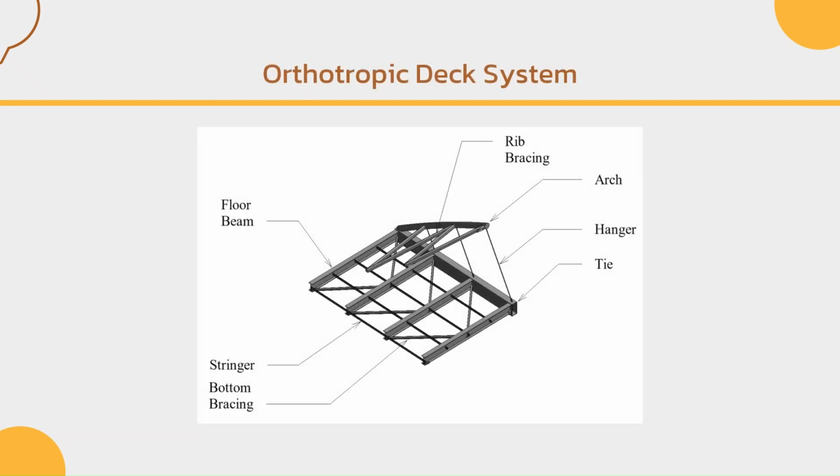Regarding the deck, an orthotropic steel deck system was adopted. This type of deck is commonly used in steel bridge structures because it is lighter than conventional reinforced concrete and precast concrete decks and provides high stiffness with efficient material use.